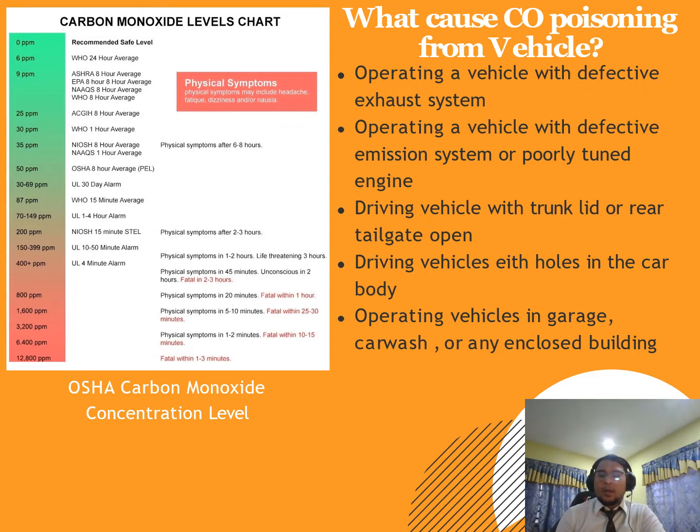Besides that, what causes CO poisoning from a vehicle? Based on the question, first, operating a vehicle with a defective exhaust system and emission system. Second, driving a vehicle with the trunk lid or rear tailgate open. Third, driving a vehicle with a hole in the car body. And lastly, operating a vehicle in a garage, carport or any closed building will cause CO poisoning from the vehicle.